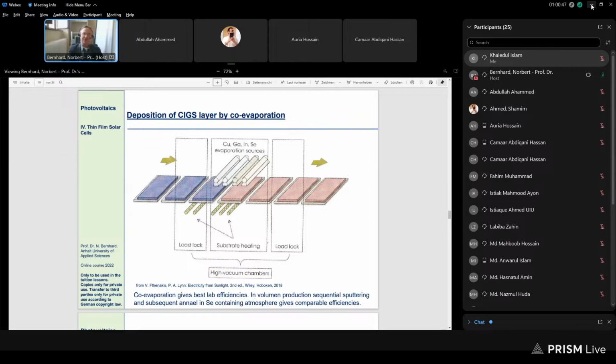Here we have a deposition vessel which is run at a pressure between 10 and 100 torr at a temperature of roughly 800 degrees centigrade. And you see here we have the cadmium telluride crystals. And then we have here the substrates coming, heating to roughly 600 degrees centigrade. Here you see we have a carrier gas which comes into this heated volume of cadmium telluride.